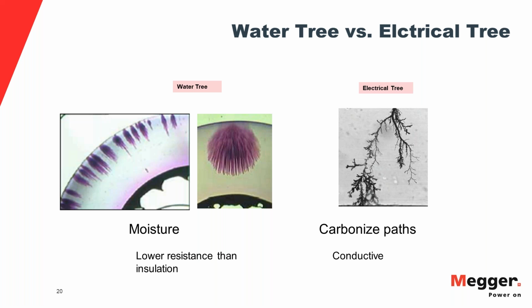No, not at all. Actually, what happens when you do the leakage current trending, again, it's a trend, okay? You have to look how it changes over testing time. Well, you have 3 scenarios, right? You can have a decreasing, increasing, or a stable leakage current. If it's increasing, there's probably a low resistance fault somewhere, the cable might hold the voltage in the testing time, but the leakage current goes up, and there's a condition.